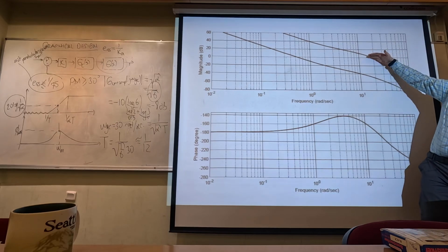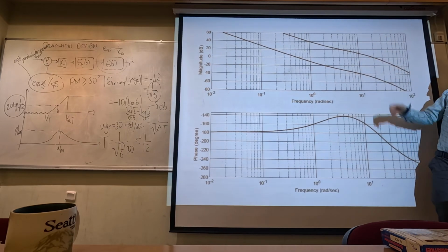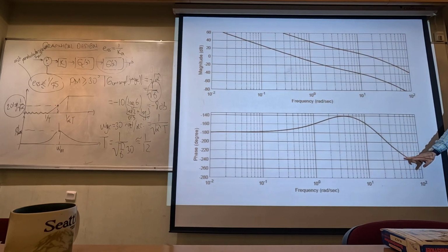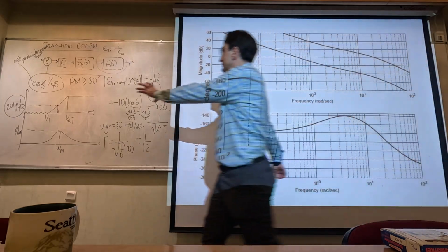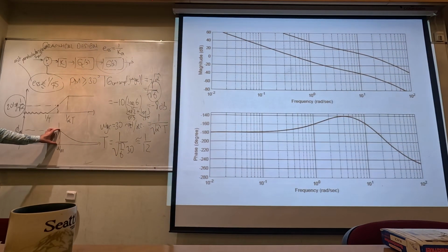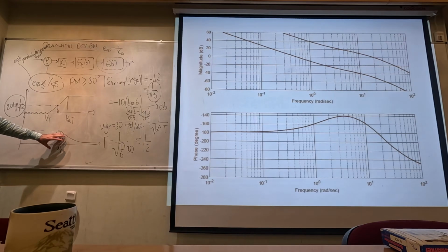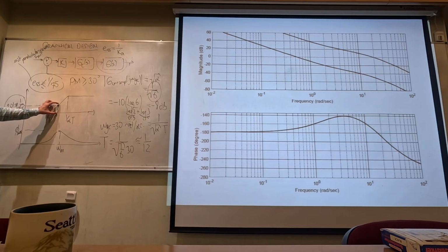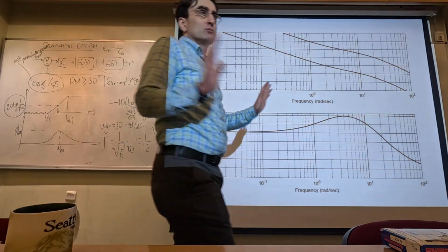If you increase the gain further, you would decrease the phase margin of the system. So you cannot do it by pure gain anymore. That is why we use this compensator to actually boost the phase with the phase waveform here, while trying to overcome the magnitude increase. With pure gain, you can no longer do it.